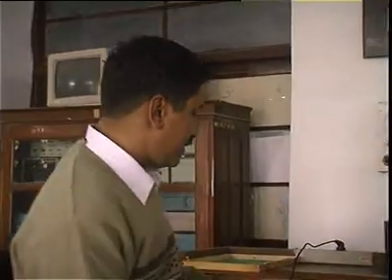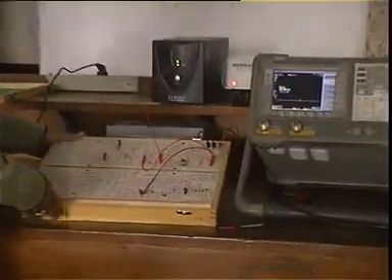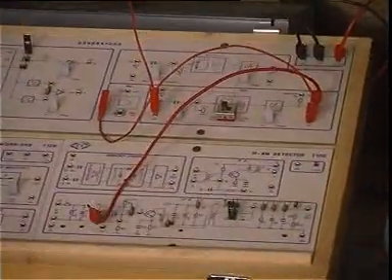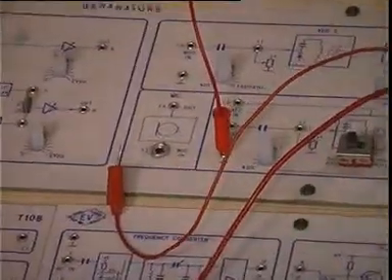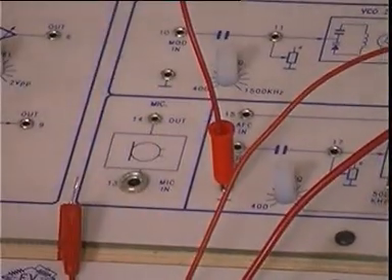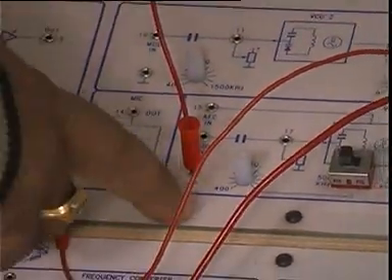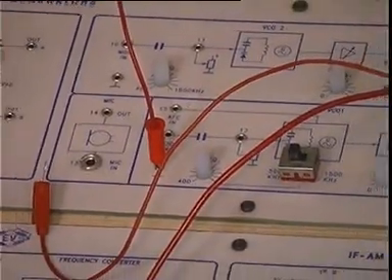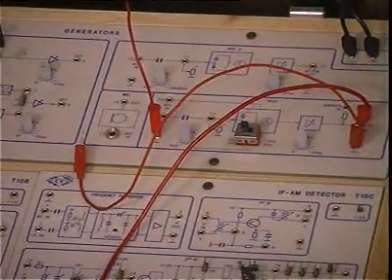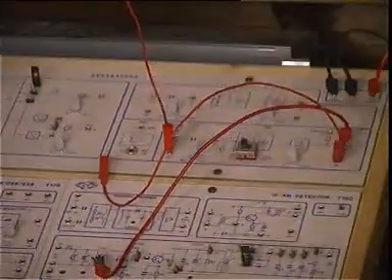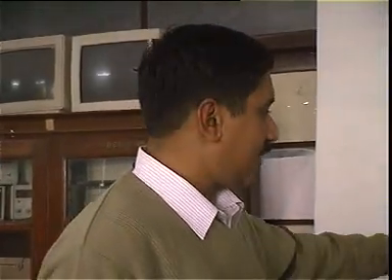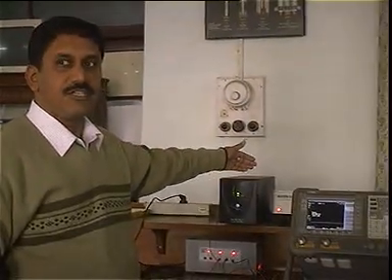Now this is a kit which is generating the frequency modulated signal. In this kit, you will be aware when we talked about amplitude modulation, we talked about the carrier signal. Now this circuit is a voltage controlled oscillator. That is, the oscillator's frequency changes depending on the input voltage. The input voltage or the message bearing signal in this case is a simple sinusoid, a sinusoidal signal that I have taken from the function generator.